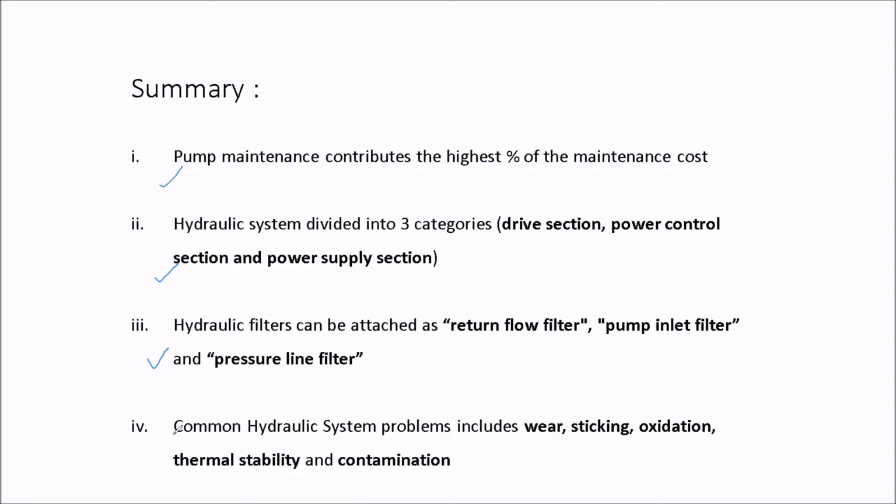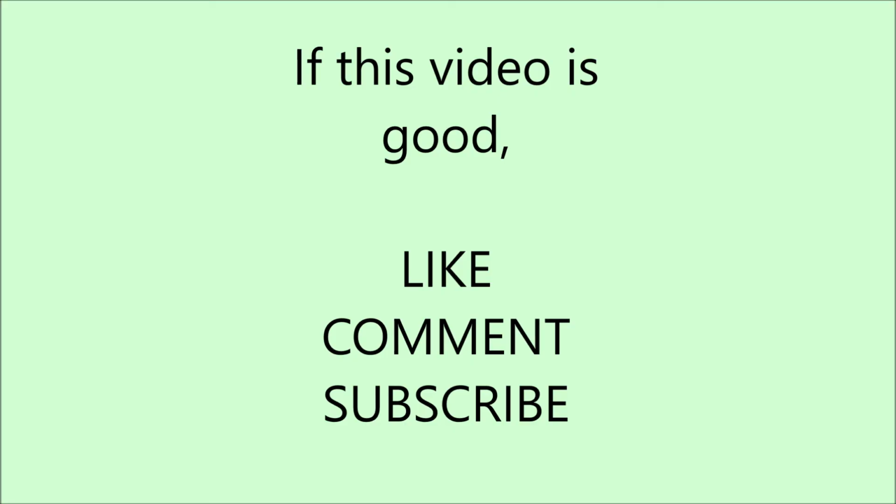Finally, you looked into the problems you have in a hydraulic system. You have wear, you have sticking, you have oxidation, which causes varnish. This creates varnish on the hydraulic component surfaces. And then you need oil with good thermal stability, and you need to watch for contamination.